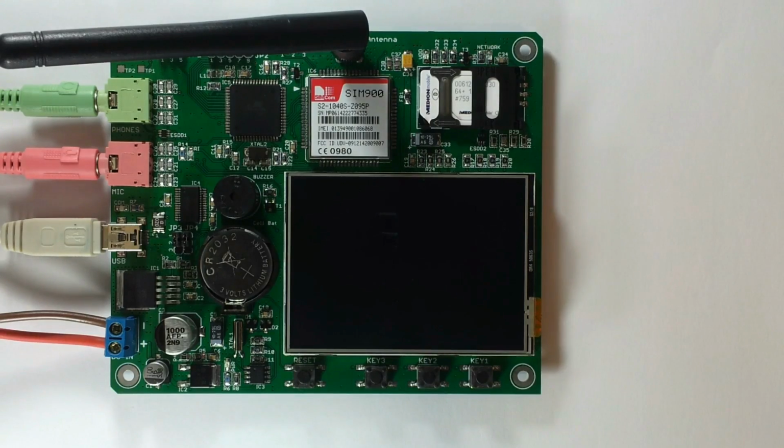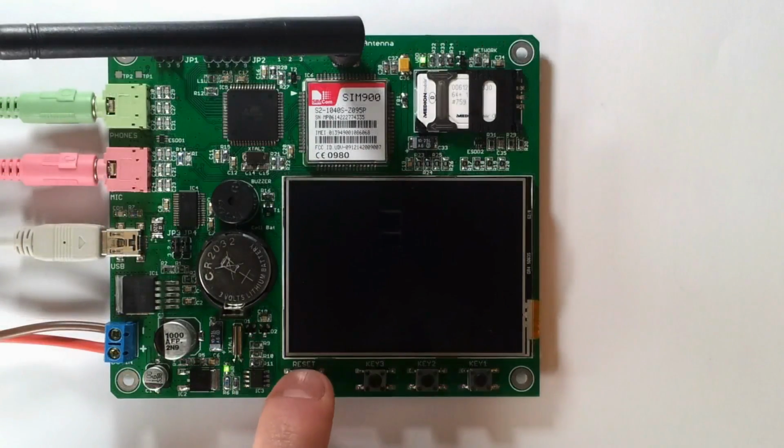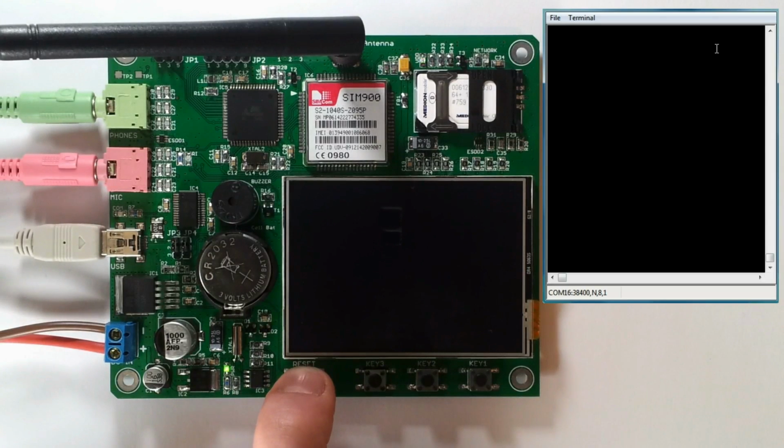And that's it. Now we're ready to power on, and I'm gonna open a terminal window on my computer, and we're gonna keep an eye on that too as we watch the board. The power is now on, and I manually hold the AVR in reset by keeping this reset button pressed, just to show you guys what happens when it starts to boot. As soon as I release this key, the reset line goes high, the code starts to execute.